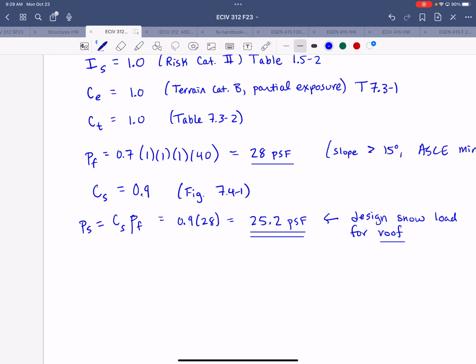So when you're looking for a live load on a specific column or a live load on a specific beam, that's when you would go through the process of identifying, can this live load be reduced? If so, how much can we reduce it based on the tributary area of that specific element, okay? So I just wanted to throw that out there because I figure that might be a helpful bit of information for you as you work through that problem.